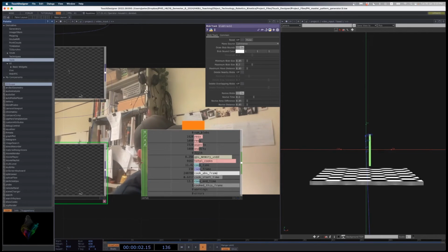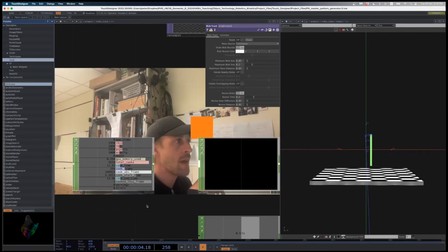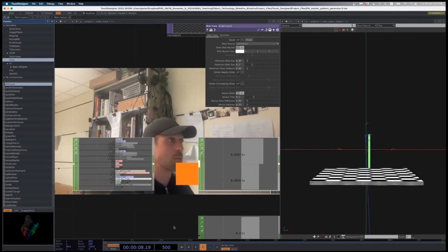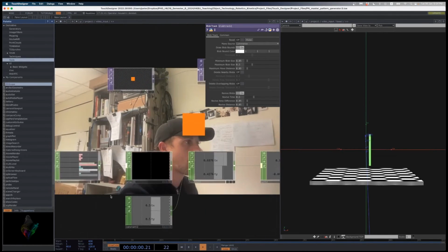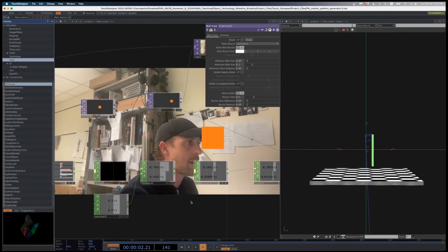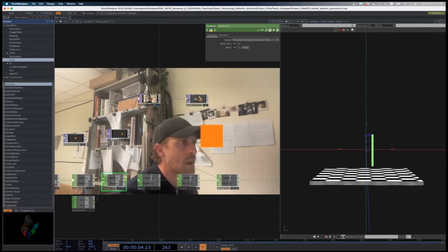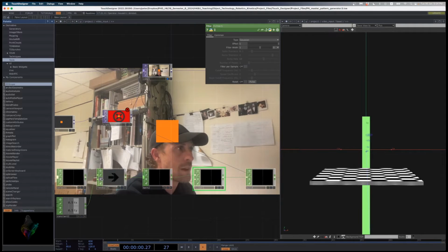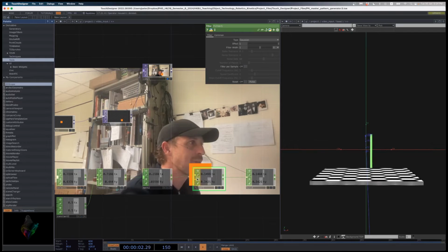But see the way this signal's jumping around a lot? That would be terrible for the robot, right? The robot can't just randomly move all over the place. So the really nice thing about Brian's tutorial is what goes on here, this little bit of feedback and this filtering. If I turn the filter off, it'll get really jumpy.